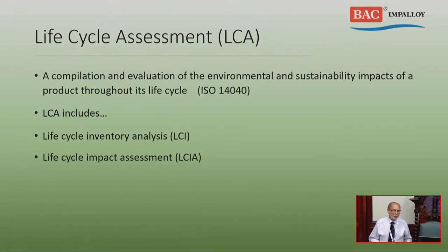It is related to the locality, whether it's near an estuary, it's related to tidal flows, and on top of all that to wave heights. So this new standard takes into account and introduces a concept called frequently wetted depth, and the designer can choose how much surface area he introduces into his calculations.